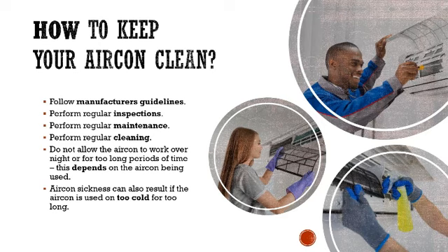Now, there was a difference in opinion on how often this should be done, but the consensus was, how often are you using the air conditioner? So if it's in summer and you're using it pretty often to keep the environment cool, then a few guidelines were: every week, make sure you have a regular inspection, but we would perform regular cleaning every month. So that was pretty much the consensus between the 4 air conditioning technicians that we spoke to.